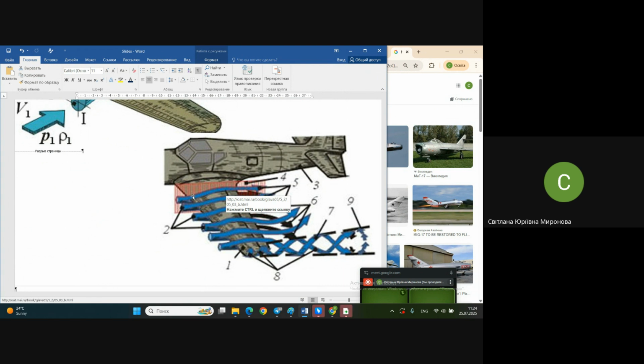When it's a swept wing, these downwashing flows are directed from the root toward the tip with some deviation. In this case, it may happen that vortexes appear out here, like bottom air. You remember that here is the higher pressure, and here is the lower pressure, and there is some invisible barrier where they meet. This barrier really does not exist. It exists only in our imagination.